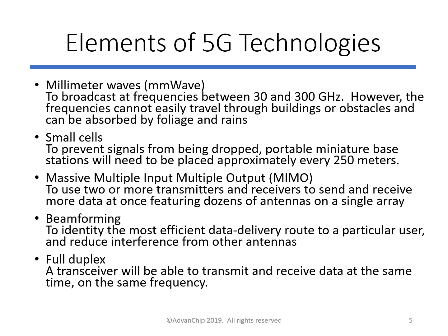Installing so many antennas to handle cellular traffic also causes more interference if those signals cross. That is why 5G stations must incorporate beamforming. Beamforming focuses a signal in a concentrated beam that points only in the direction of a user. This approach can strengthen the signal's chance of arriving intact and reduce interference for everyone else.